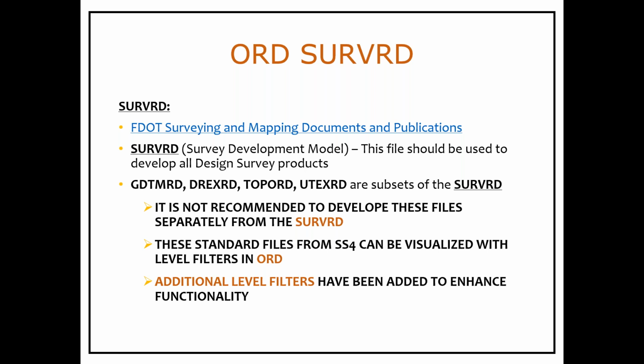These standard files from SS4 can be visualized with level filters easily in ORD. Also, there are attachments through the attach survey workflow. If you go into the OpenRoads Modeling workflow and look under the FDOT tabs, you'll find attach survey.